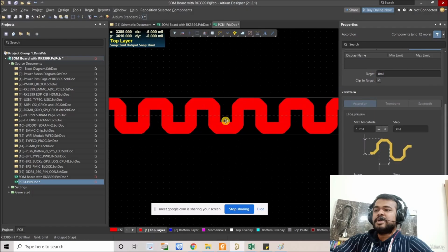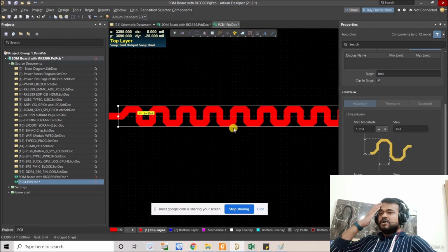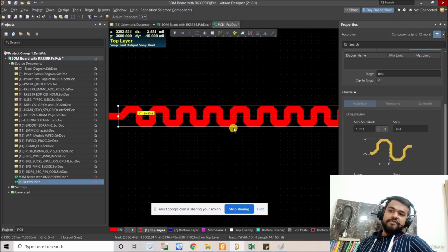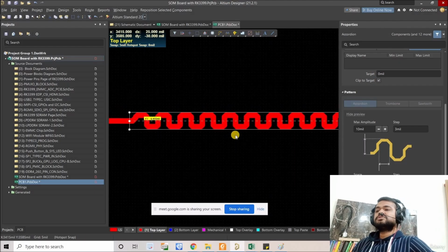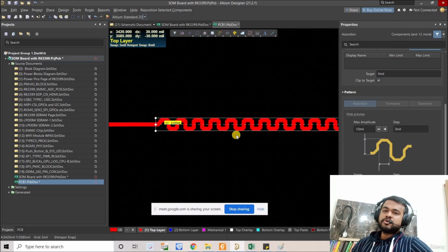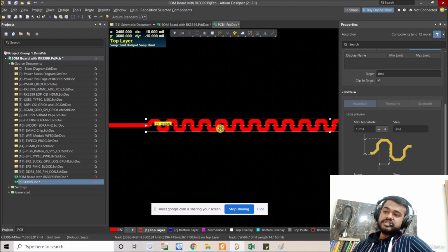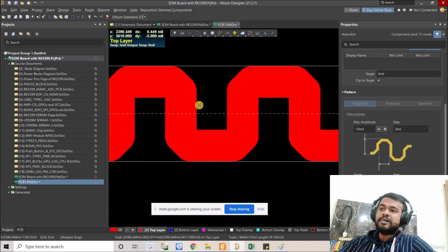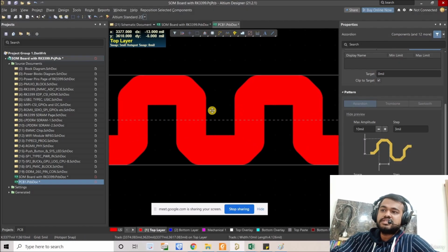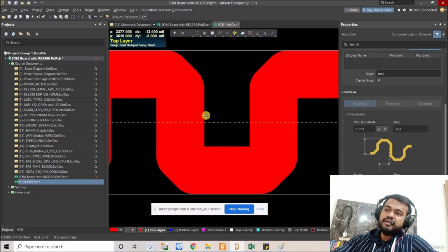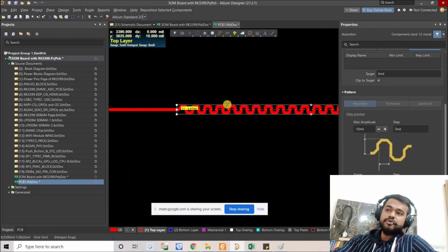Now, what is this space parameter? Just go to that clearance point that we discussed at the start of this session. What were those clearance points? Those were either 2 times or 3 times the width, right? So the same rule we have to apply here, because there can be interference on the same line as well, right? Because these are coming closer, and at a particular time instance, you can see different voltages on these two lines, right? And there can be interference. To avoid that, we follow the same rule here as well. That's why they have given this space.